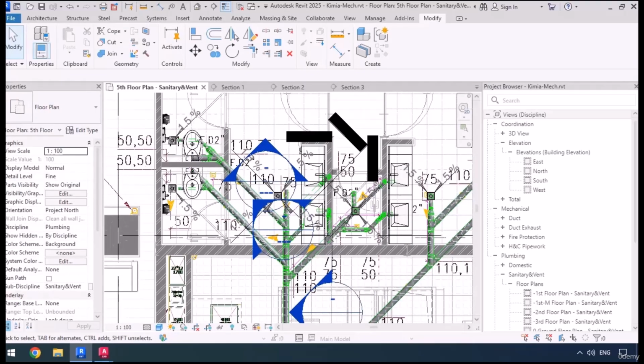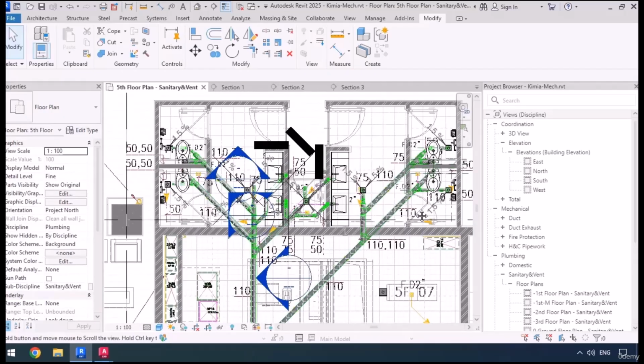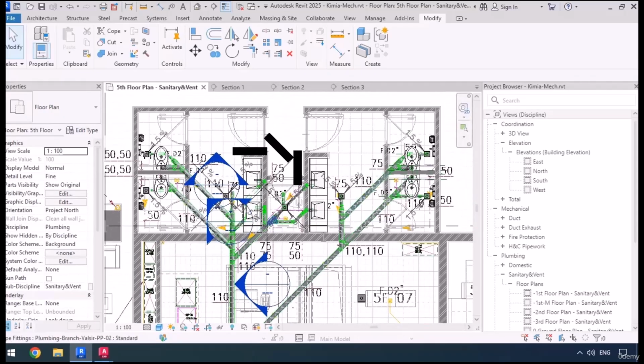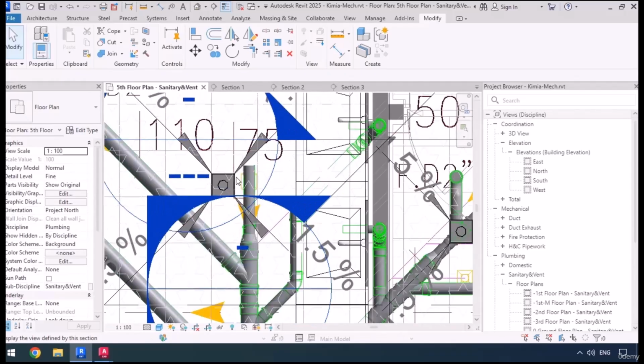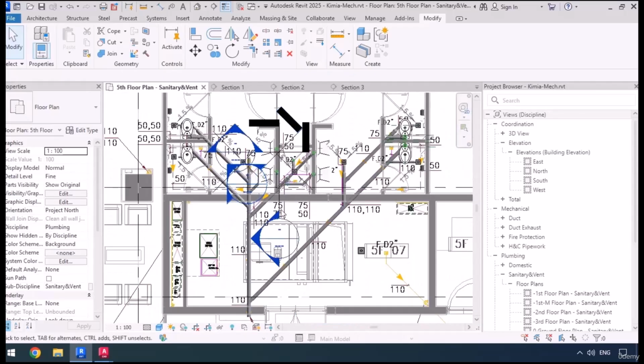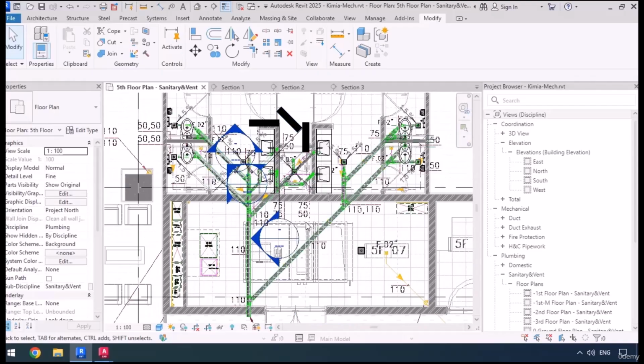Now as for the pipes connecting to the toilets and the floor drains, we've got the same thing that we did for this side, and the connection to this floor drain is the same way as well. But before we do anything, first we're going to have to place a comment here and state that this floor drain needs to be moved a little more to the right, because it wouldn't be physically possible to have an elbow and a branch leading from here, and also place the trap and the other fittings as well. So we're going to need to place another comment on here.